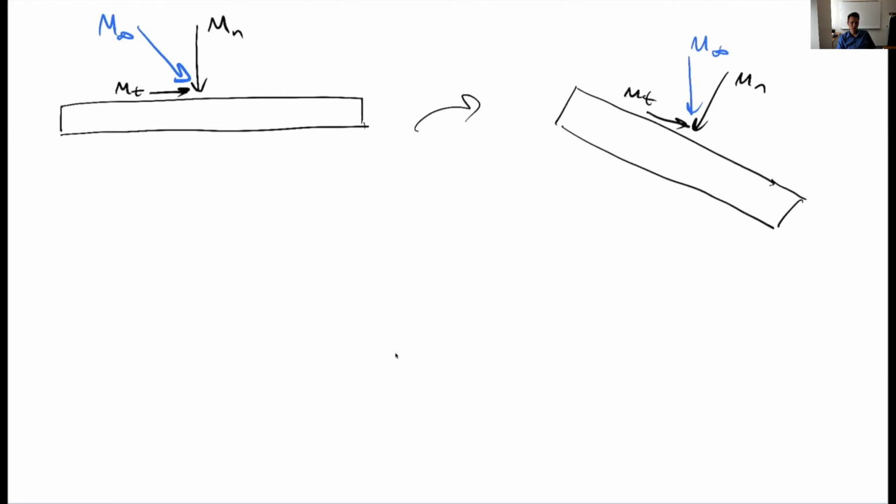And indeed, this is not a perfect analogy, but it works surprisingly well, this simple idea. There are some formulas in the text and more sophisticated ones you can find in various published papers, but you'll see predominantly this cosine of the sweep angle appear in these, because again, this normal Mach number plays a critical role in the physics of the problem.